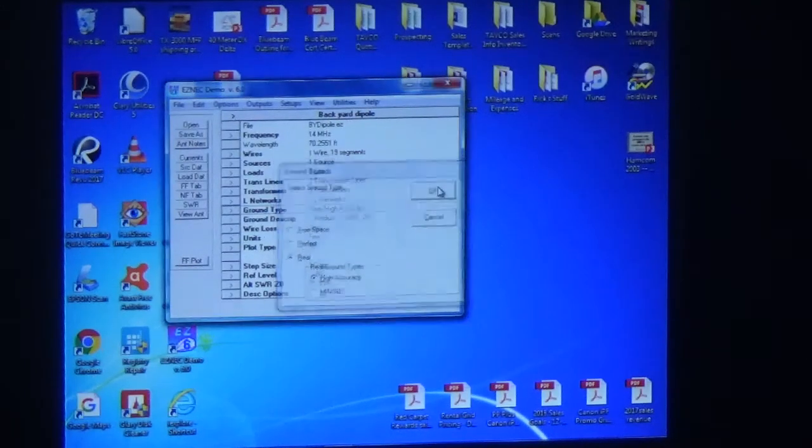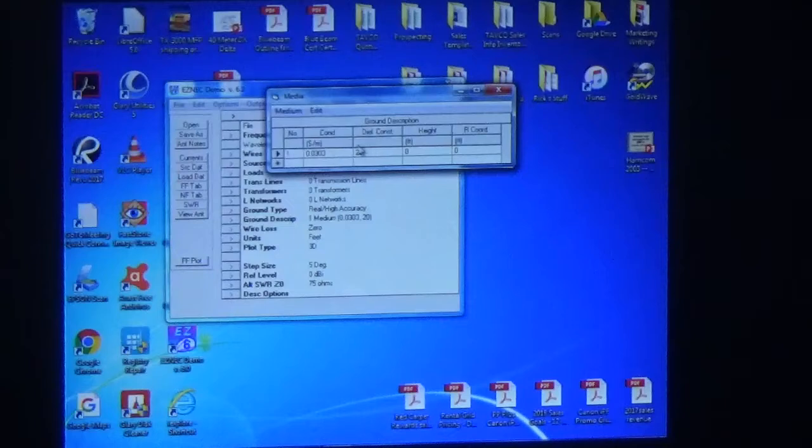Now you can define what the ground is: Siemens per meter, dielectric constant, things like that. It depends on your area. Some people have great ground. Some people, up in Nevada, may have terrible ground. How do you get a measurement of that? In the ARRL handbook, they have a really coarse map that has contour lines that show you what that is, and you can see big differences.